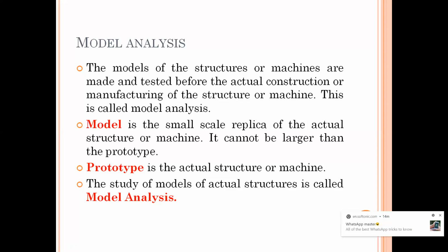For example, I'll take the example of a Pelton wheel turbine. I make the same setup in a smaller version, make water pass through it, and see what the efficiency is for different heads and different discharges. Then I change my design or some of the measurements to see where it works best. And once I fix the design, I will scale it up to a prototype.